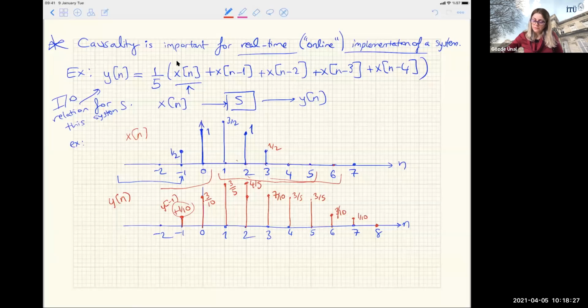And then at 8, it's going to be 0, and it was 0 before here. You see how it's calculated, right? I'm shifting a window of 5, summing things because it's the same weight, 1 over 5 for all the coefficients. That's why it's easy to do here. This is called a 5-point running average filter.